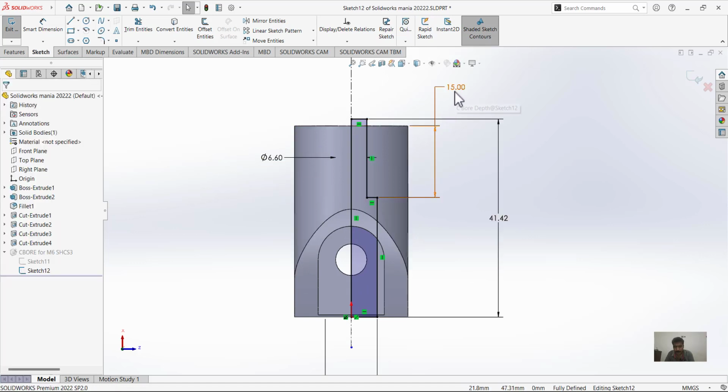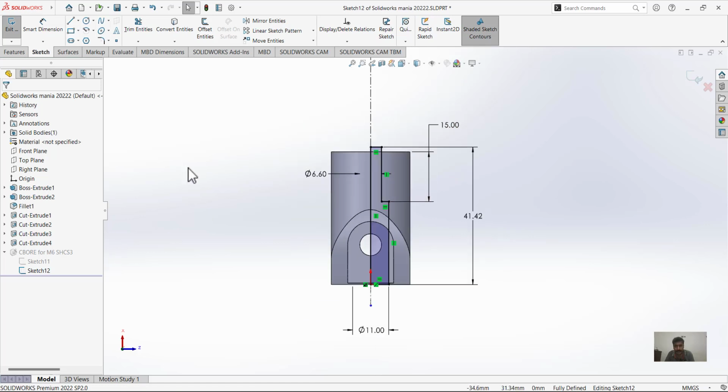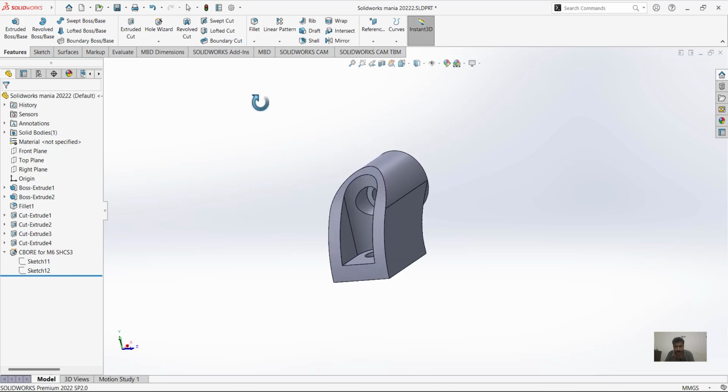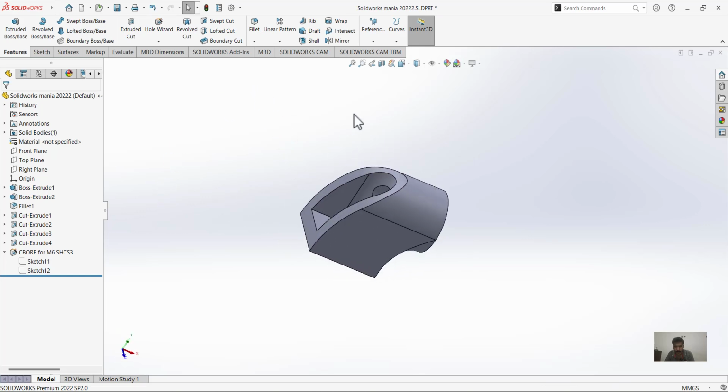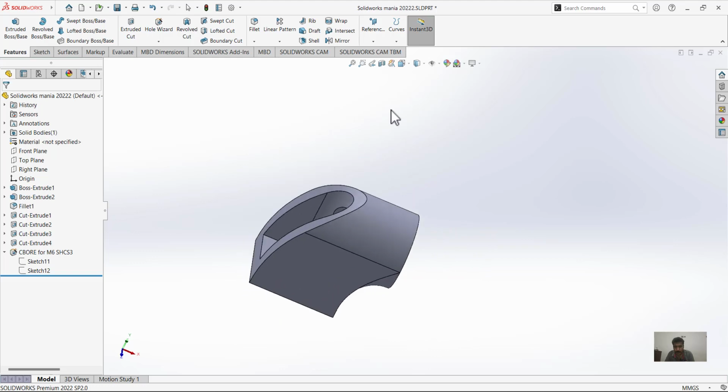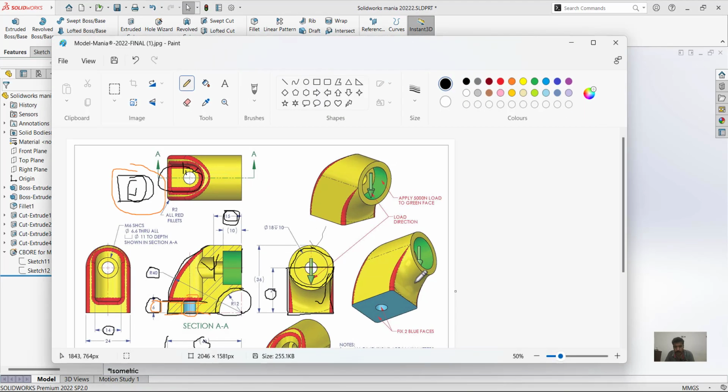That's the mistake I was making. I was deleting this dimension. We are not able to delete this dimension because this dimension is already stored in this command. So by deleting it, it will show me the error. So if we just change the reference point from this one to this one, this dimension is there, but we can edit it. Let's see if we, yeah. So I think at this point, we completed most of this stuff.